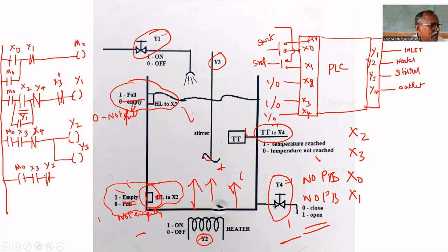But at the same time, does any other thing have to be included? X4 is included in the record note. But if you think practically, it will not work out. But here in simulation, it will work. We will keep X4 at 1. In practice, before 5 minutes the temperature will fall, meaning that the value will change, so it will not work out. Anyhow, if you want, you can include that also, X4. Then we have to put the timer. So let us assume that the temperature is at the set point. So now we can put the timer.